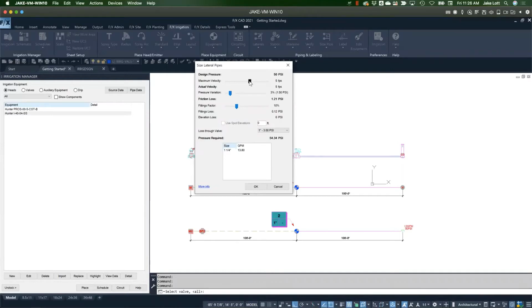And so if we're trying to squeeze a certain amount of flow into a pipe at a certain speed, and we're still speeding it up and we're still trying to fit it into that pipe, there's going to be a higher and higher friction loss, which means our pressure is going to drop. So this is the magical part of this math stuff that, if you start to think about it too much, it doesn't make sense. So I try to move along a little bit quicker, but I just want you to see that correlation.